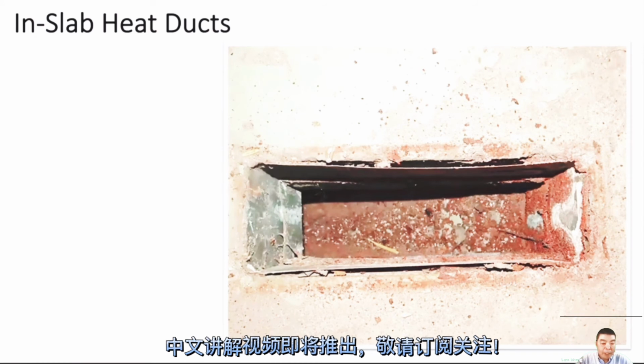Any moisture, rust, mold, and so on should be documented in your report, just make notes. I don't know if there's any way to repair that, because it's hard, you even need to break the concrete. Now maybe you cannot see an in-slab heat system like this, most of the time we cannot see it.